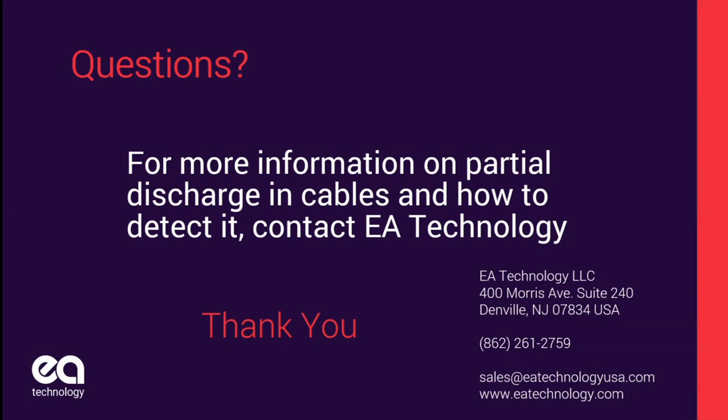Does PD measurement have voltage limitations? Well, since we're with cables, we're looking on the ground. From a safety perspective, it shouldn't affect it. Now, PD is a voltage-driven event. When the voltage is higher, you'll get PD. When the voltage is lower, the PD may stop. So it doesn't affect the measurement, but it does affect the presence of PD or not.